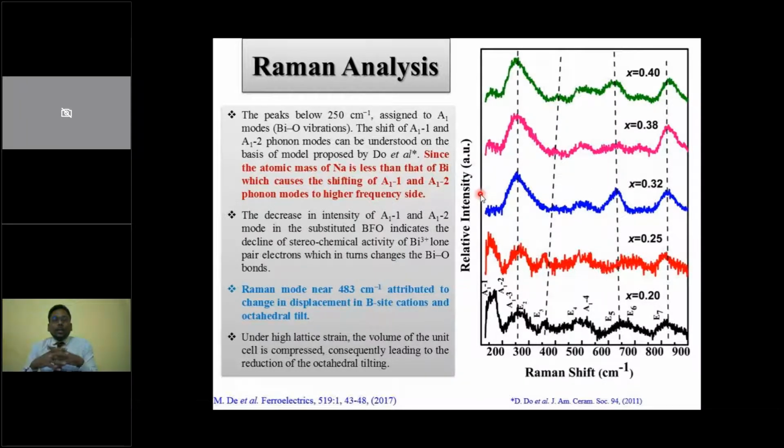that gets restricted. Similarly here in material science, when a foreign atom is doped or makes a solid solution with the material, then the lattice vibration, known as the phonon mode vibration, gets restricted at a particular site. By Raman analysis we can find this type of phonon mode and how it changes with the doping concentration.